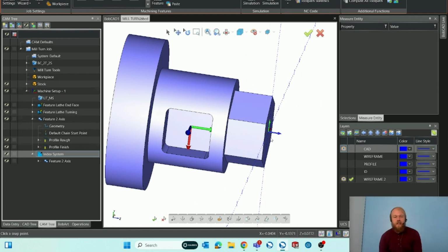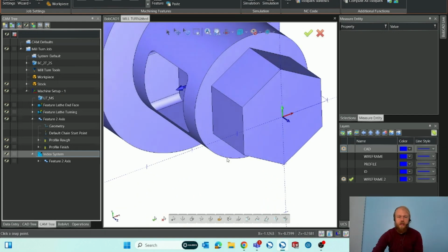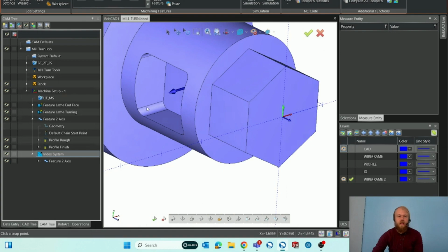I did have to ask that question recently. Just wanted to make sure because that's newer in the newer versions here. The X and Y values, they can be rotated around like that. That is okay because the only thing that really matters here is your Z axis. And everything, again, is referenced from your G54 location anyway.